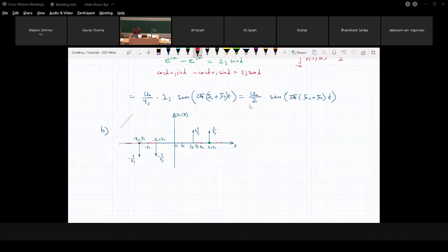As you said, we have to remove negative frequencies. So I remove all negative frequencies. Then I have to check with respect to which frequency we perform the transform: Fc or Fs? Fc, yeah, the carrier frequency. Let me write the intermediate spectrum again.